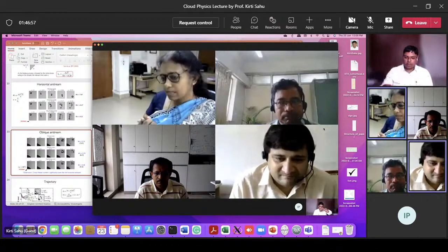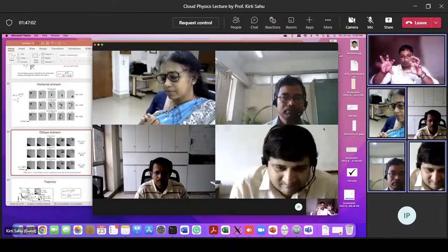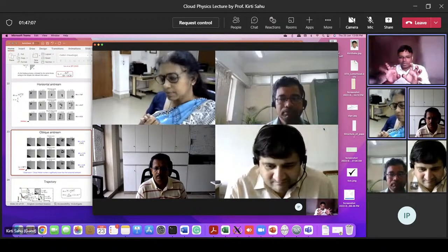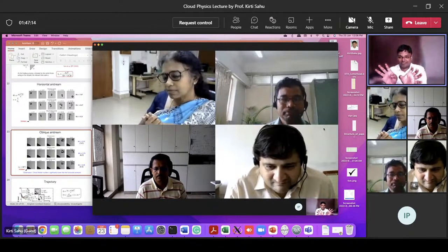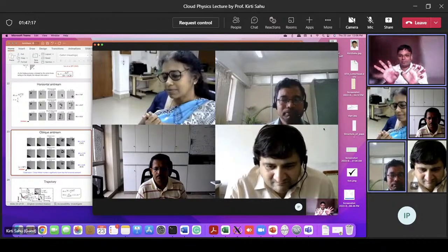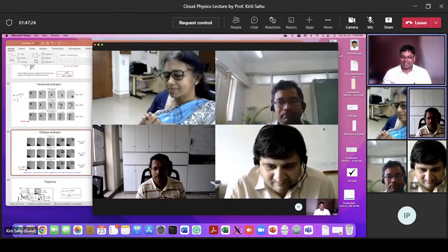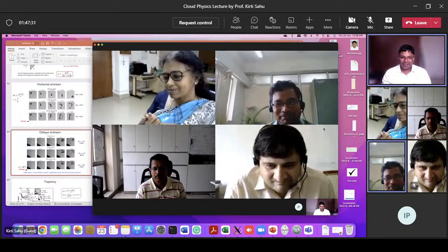You're right. So regarding this coalescence, what I was saying is, if we have two spherical drops to start with, they will fall spherically. So there is no reason for them to coalesce because they are falling vertically. They are not hitting like this. But now if we have these oscillations, if they come closer and hit each other, they will just merge because there is an extra force. So that is essentially one mechanism I came up with for why our drops can coalesce more.